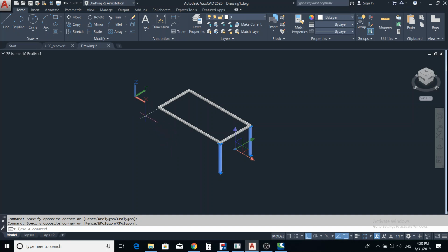Is that okay? So let's say, for instance, I want to move this to this point. I'm basically traveling along the x-axis. Do you get the point? And the plane that is perpendicular to this x-axis is the y and then z plane. So yz becomes my mirror plane. So I will go by again, 3D mirror, click this point. I will have to travel along the y-axis and then the z-axis, enter.